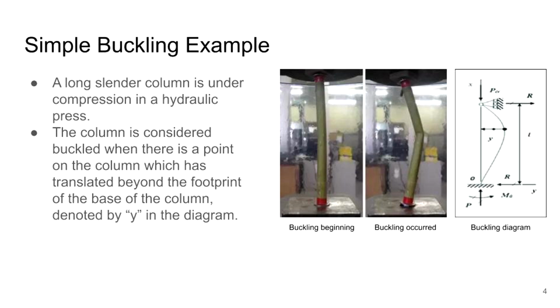A short column under the action of an axial load will fail by direct compression before it buckles, but a long column loaded in the same manner will fail by springing suddenly outward laterally in a bending mode, which is buckling. The buckling mode of deflection is considered a failure mode, and it generally occurs before the axial compression stresses can cause failure of the material by yielding or fracture of that compression member.